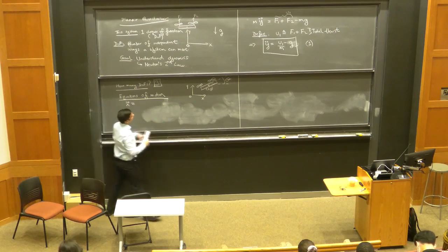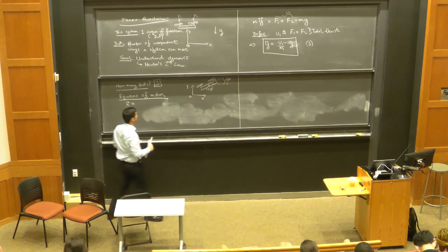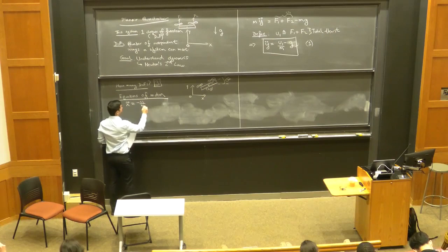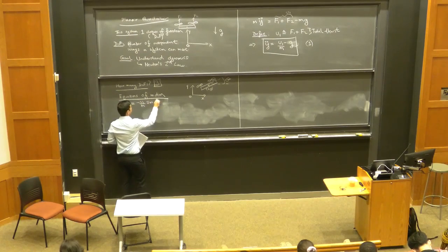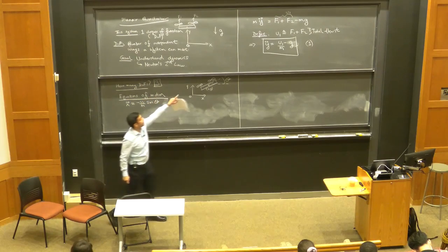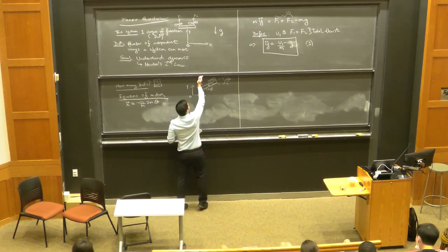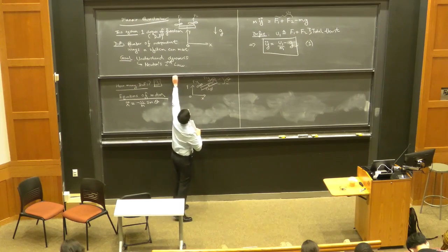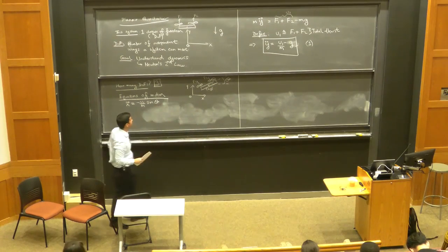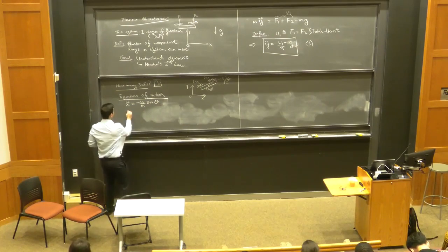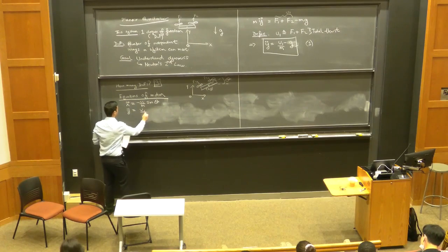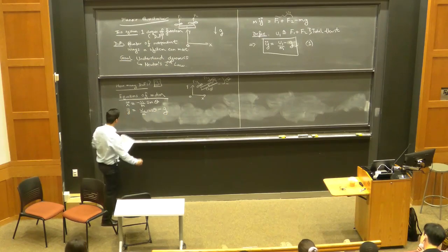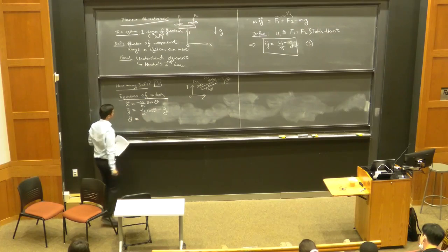x again is the location, xy gives you the location of the center of mass of the drone. So x double dot is minus U1 over m sine theta. U1 has the same meaning as what we defined over there. U1 is the total thrust, F1 plus F2. U1 is just defined as the summation of those 2 thrust forces. y double dot is going to be U1 over m cosine theta minus g.